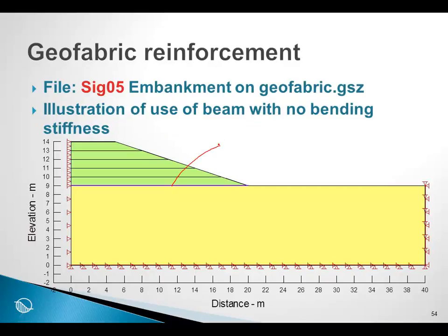our geofabric here has no bending stiffness. It has axial stiffness but no bending stiffness. Therefore, we simply set the moment of inertia equal to 0. And that way we can simulate a geofabric with a beam element.